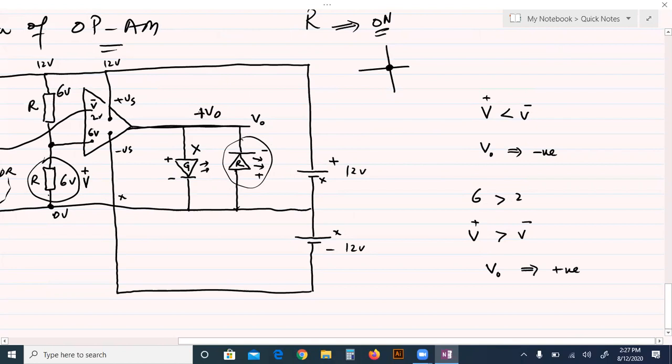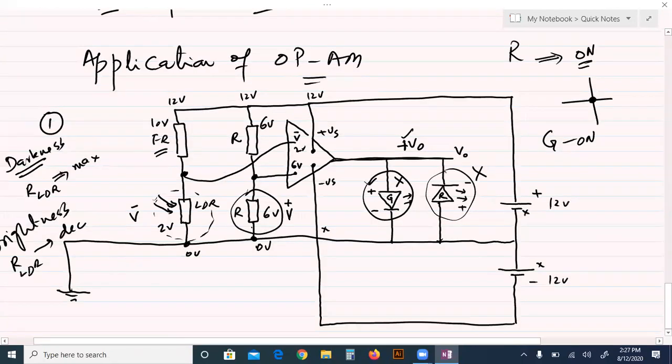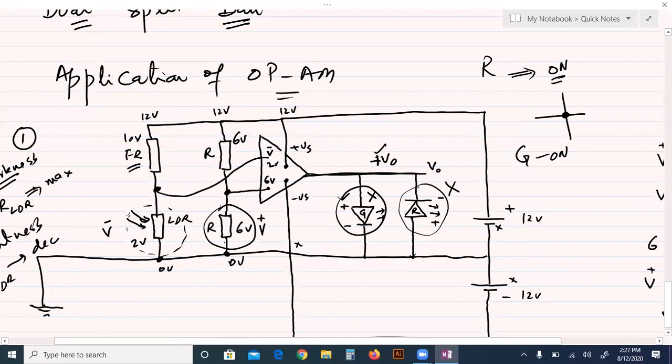So this becomes positive. Now this is reverse bias. This becomes forward bias because positive is connected with the positive. So current flows through it and green goes on. When there's darkness, red on. When there's brightness, green on. For high intensity of the light in the surrounding, this is the indicator. For the low intensity of the light, even darkness, this is the indicator, okay?